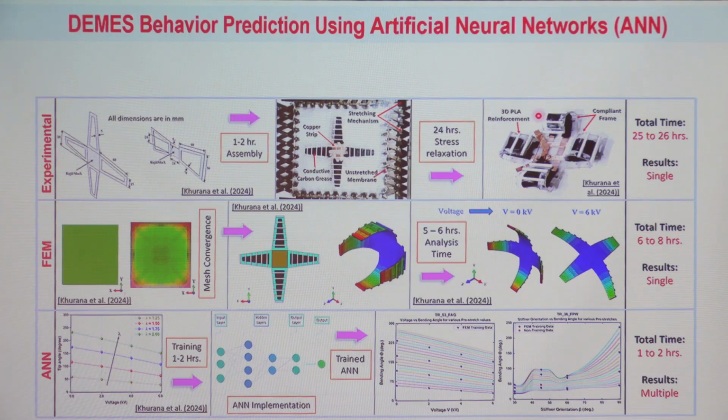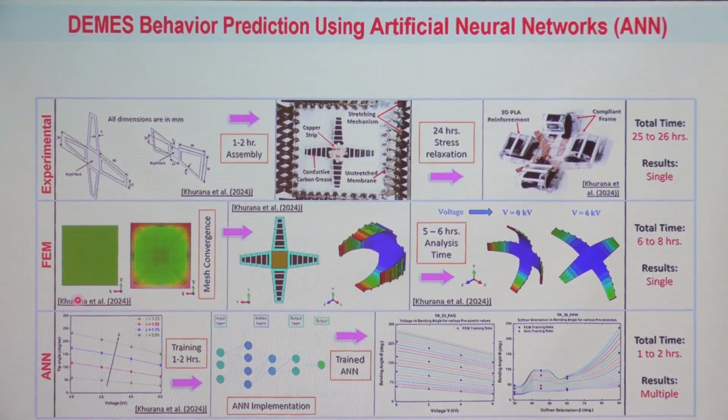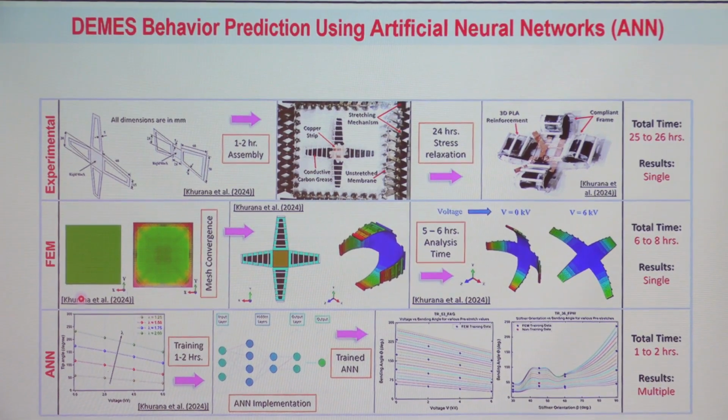And if some source of error creeps in, your entire structure will fail. So a source of error can also come in there, okay? That is one thing. Finite element: pre-stretch the membrane by applying the displacement condition, obtain the initial stresses. One simulation you have to carry out.